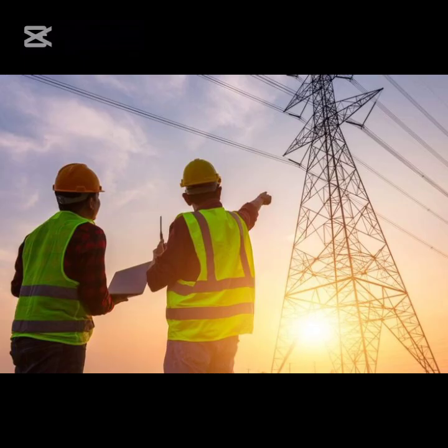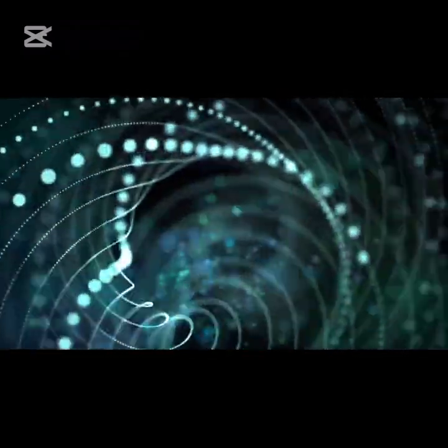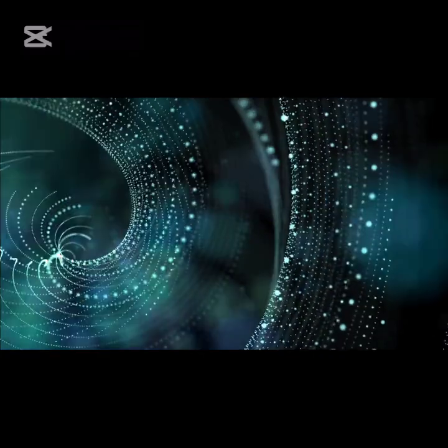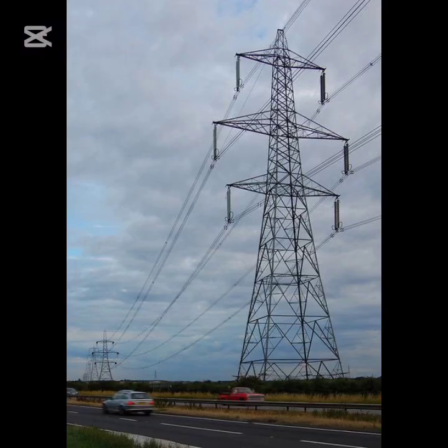7. Regular maintenance and inspection. Regular maintenance and inspection can help identify potential issues before they become major problems. This includes monitoring conductor condition, checking for signs of wear or damage, and performing necessary repairs or replacements. By implementing these methods, utilities and transmission line operators can mitigate excess sag and ensure reliable, efficient power transmission.